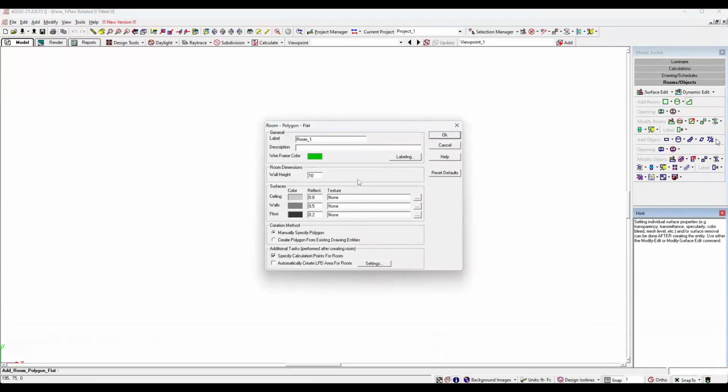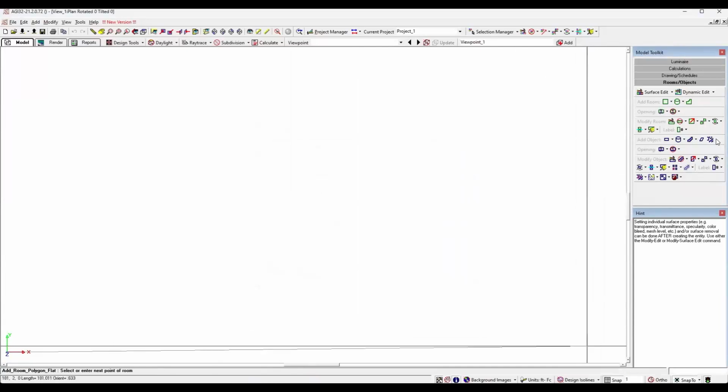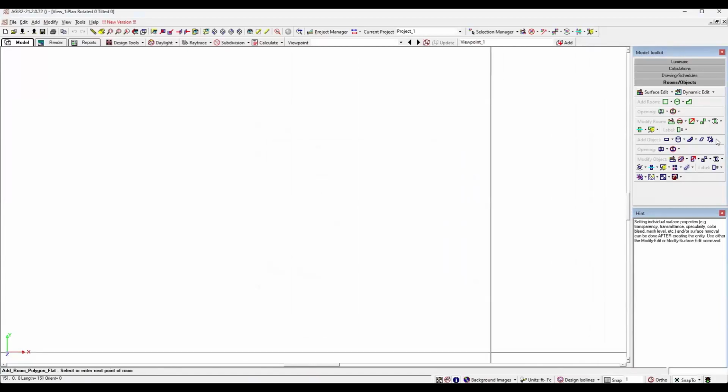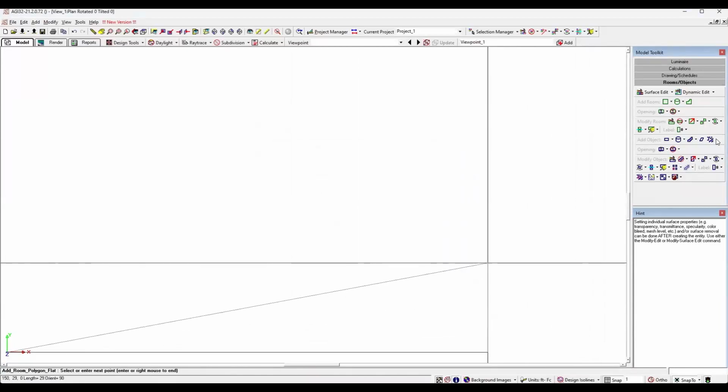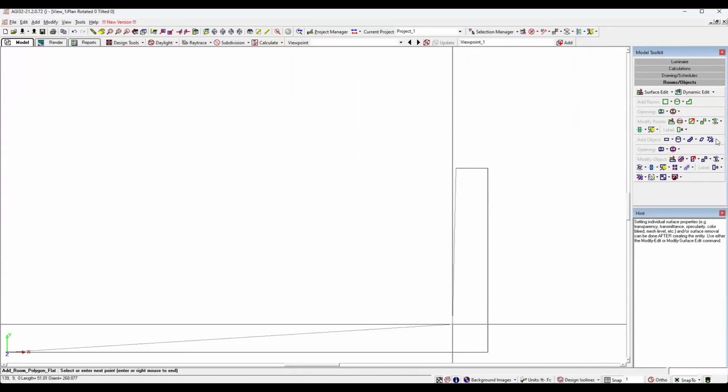In this example, we have a 10-foot wall height, so we're going to put our wall height in right now. Going to make our orientation point a little easier to find, and we're going to start by clicking right at 0, 0. We know that we have a 150-foot long hallway, so at the bottom left you see it says 150, 0. I'm going to tap there, and following along, I know that it's 60 feet tall. I'm going to tap there, by 10 foot wide, so I'm going to go to 140, and tap there. Continuing down.